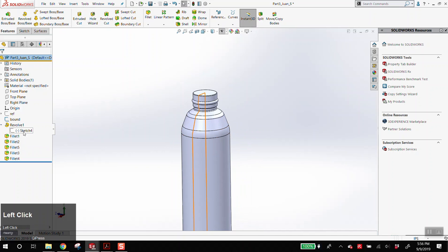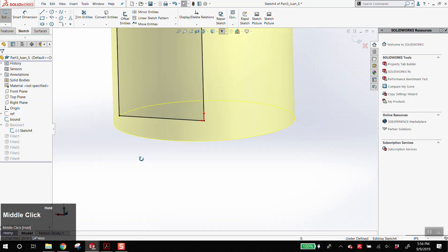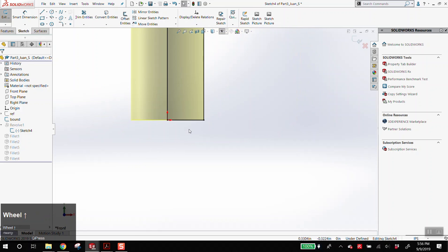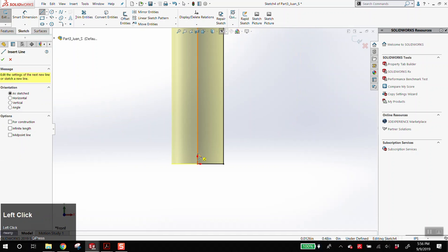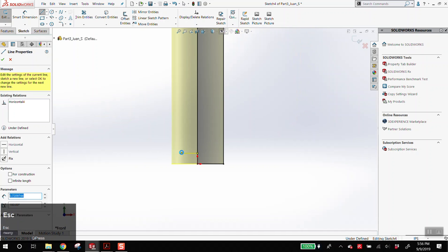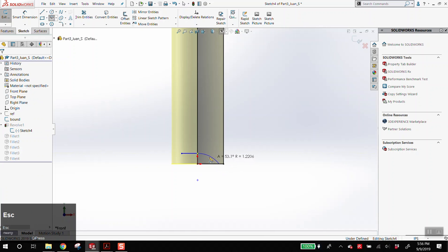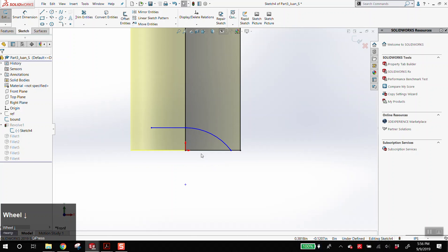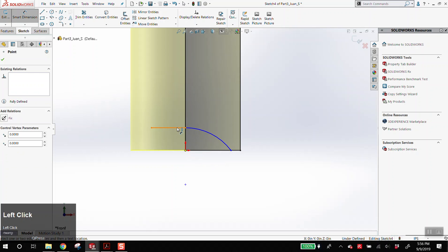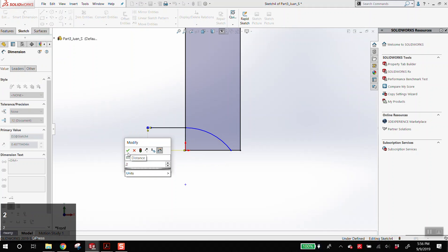I'll use this opportunity to talk about push-ups. So again, the most efficient way would be to put the push-up in this command. You could always put an arc in here. With a push-up, I have an arc, and I want this to be tangent. If it's not tangent, you might get a funny point in the middle. A good rule of thumb is push-ups are about 1/4 of an inch up, so just go anywhere from 0.2 to 0.25.